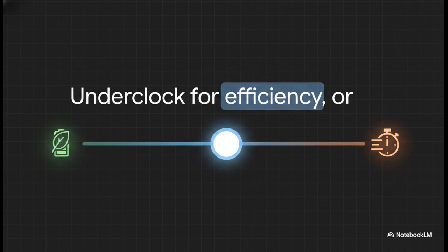On the flip side, if you're hovering right on the edge of missing a super strict service level agreement latency target, a very small vendor-approved bump in the SM clock might be exactly what you need to reduce tail latency, assuming your cooling systems can handle it, for sure.